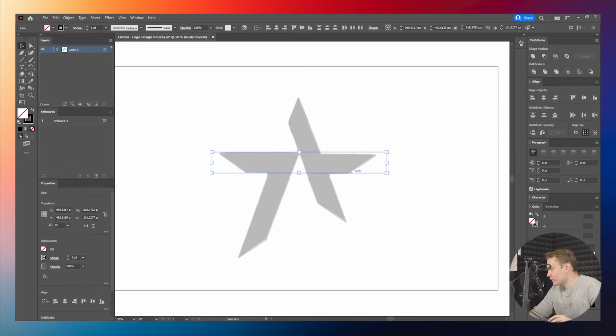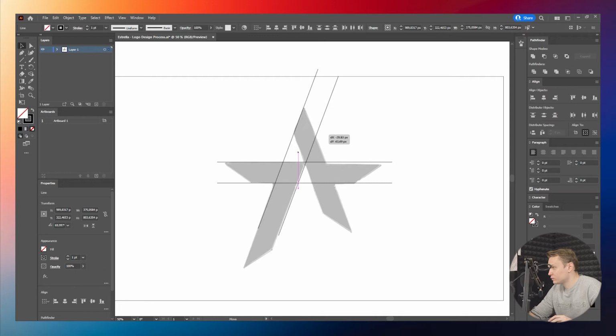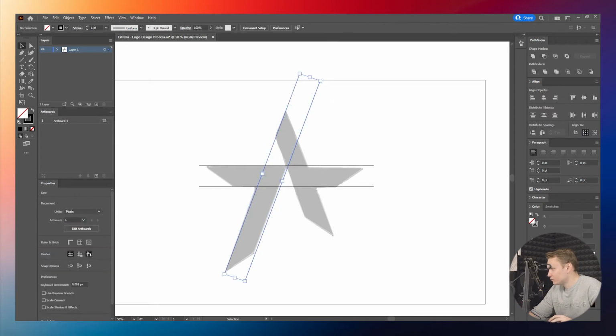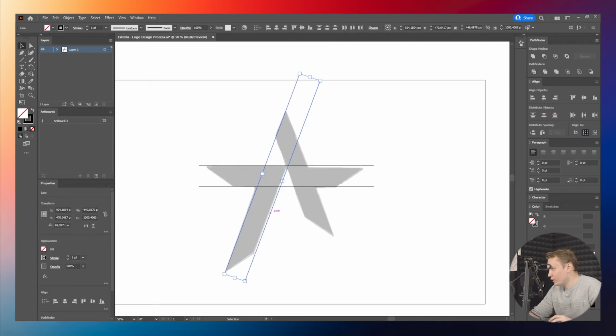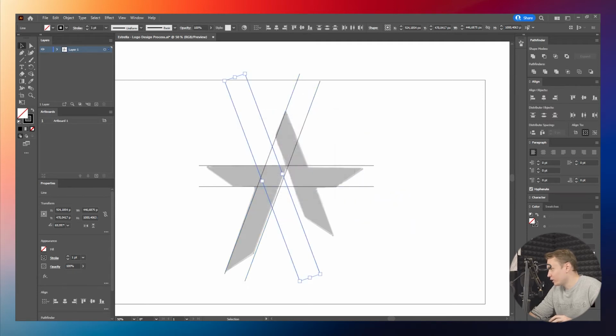Super. Select two lines and create a copy of them. And let's rotate them to the angle we need. That will be good. Select these lines again, duplicate them, and reflect them vertically. To do this, right-click on the selection and in the window that appears, select Transform, Reflect, Set Vertical and click OK. Now let's align them relative to each other.